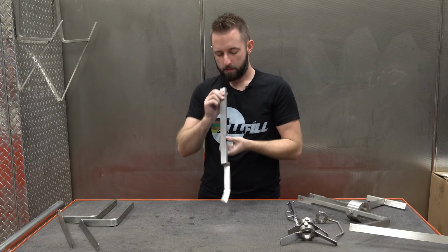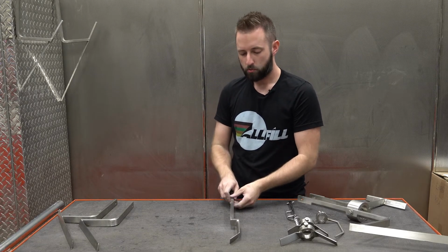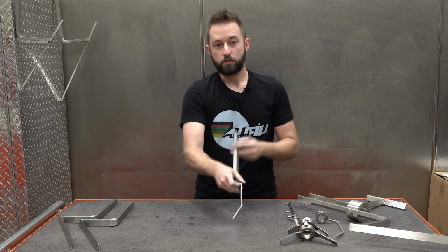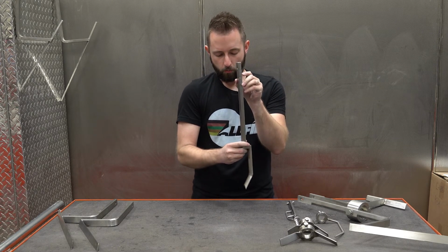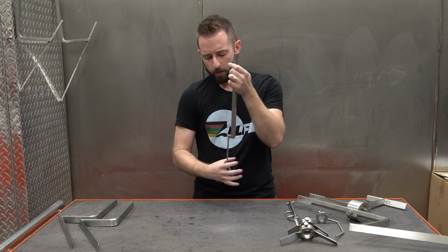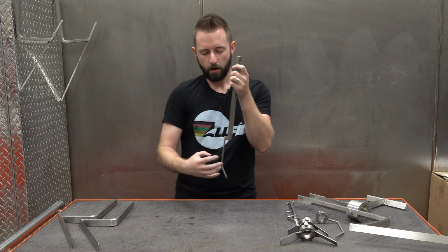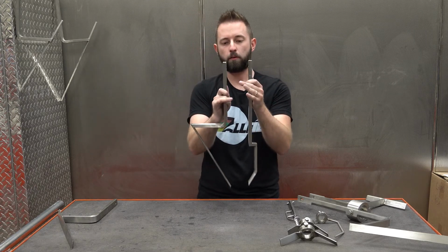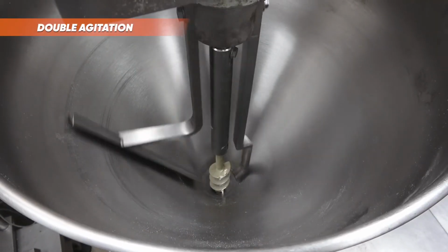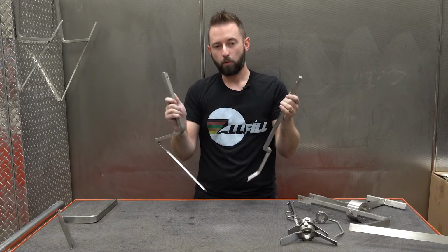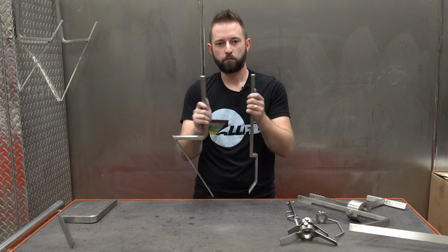Now what's kind of nice is, let's say we have a product that really has issues with feeding, that's light density or is flaky, which typically we would use this. So we would implement this flake blade, and it would rotate and help collapse that rat hole. But let's say we're having issues where the outside product isn't moving. We can actually run 2 of these in tandem on our hub with what we call double agitation, which can be 2 of this style, 2 of this style. We can marry up all sorts of combinations, but we would determine that through lab testing.